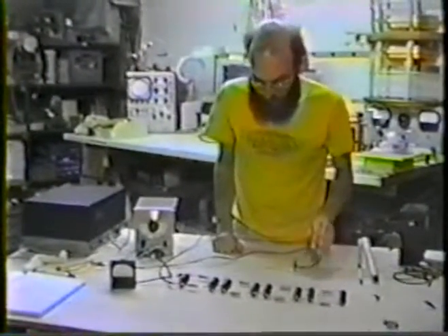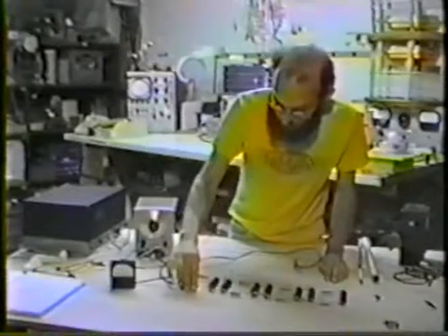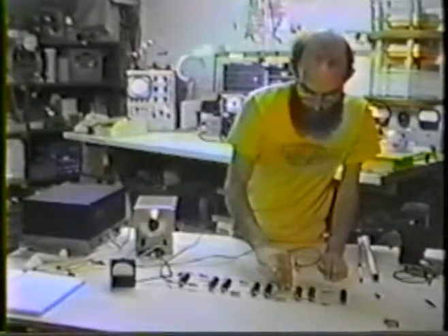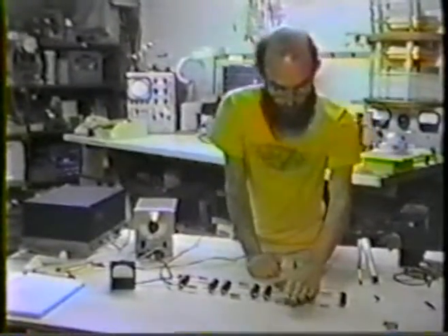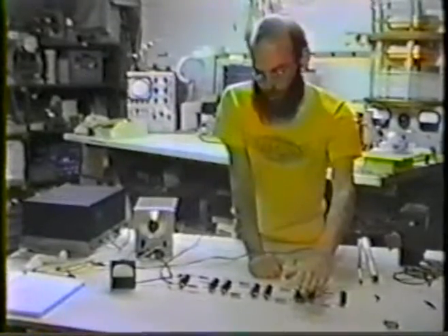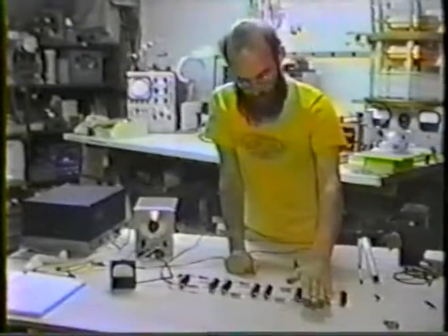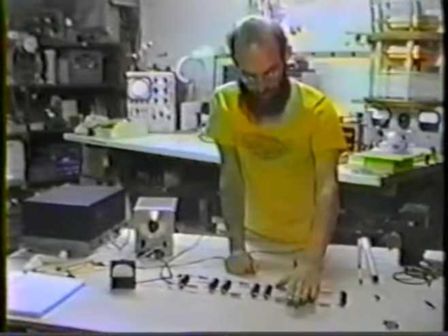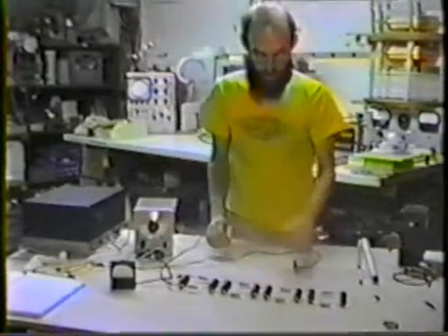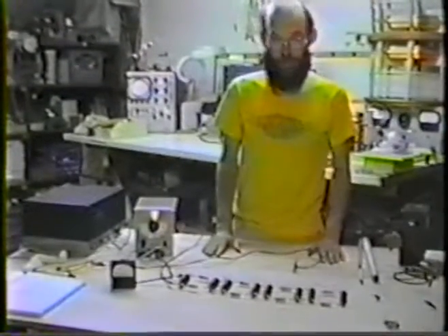And we'll do our heat check again, see where the heat's coming from in here. Feel our input coils, relatively cool. The input capacitors are quite hot. Go down the line here, capacitors are cooling off, but the coils are very, very warm here, this end. So now we have the situation where the heating effect is turned around from where it was before. Now the dielectric input capacitors get hot, and the magnetic output inductors are getting warm. So we have quite a few differences here. Now what we'll do next is we'll do some quantitative comparing of these differences, and then we'll do a few novel experiments and give some ideas for the experimenter to work with this on his or her own.